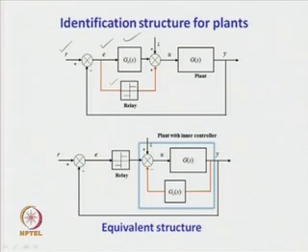So, the relay is subjected to now the plant with inner controller GC(s), and that is the prime controller we have in the system, but with this arrangement effectively all the load disturbance is present, we are not skipping anything out. In spite of that, what do we get? The relay experiences the closed loop system in this fashion. So, what is the beauty of this scheme?